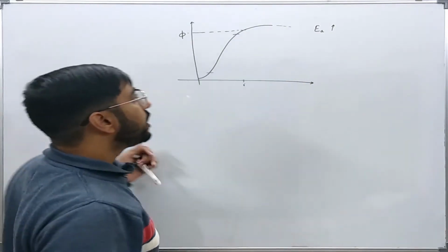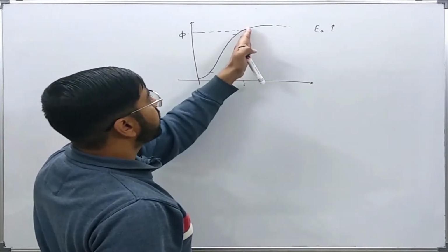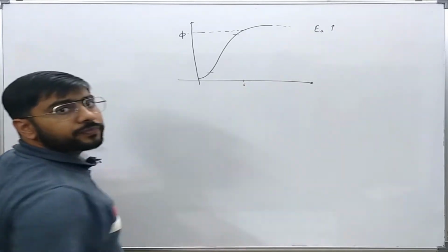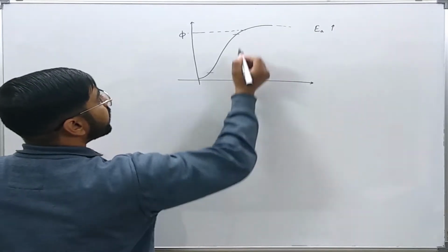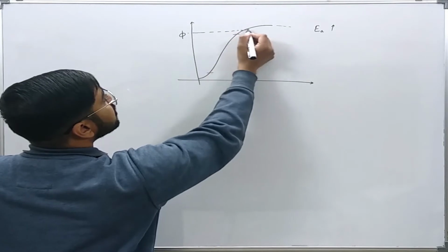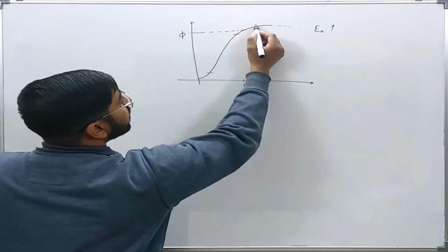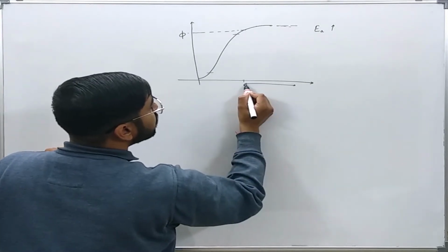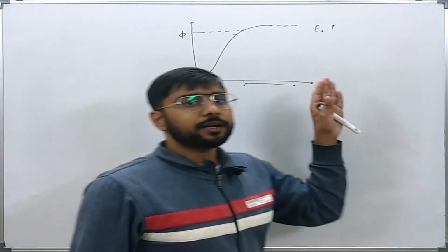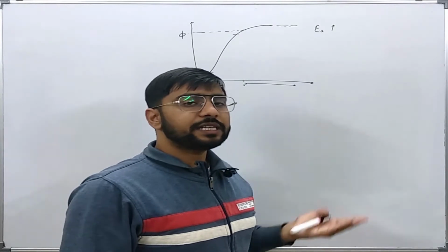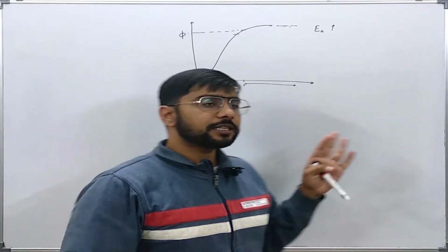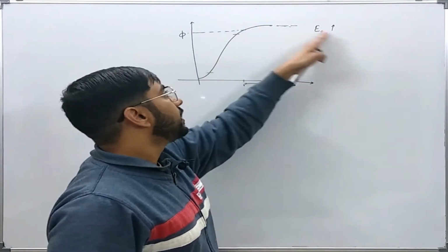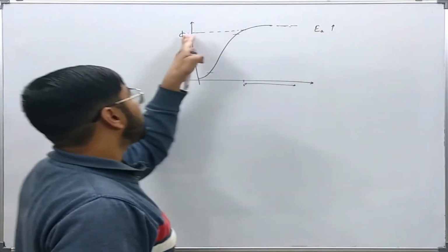However, beyond a certain limit, any increase in flux will require a very high increase in current. That increase in primary current will just cater for the increase in the excitation current of the CT. That is, it will try to excite the CT to induce the required voltage through this flux.